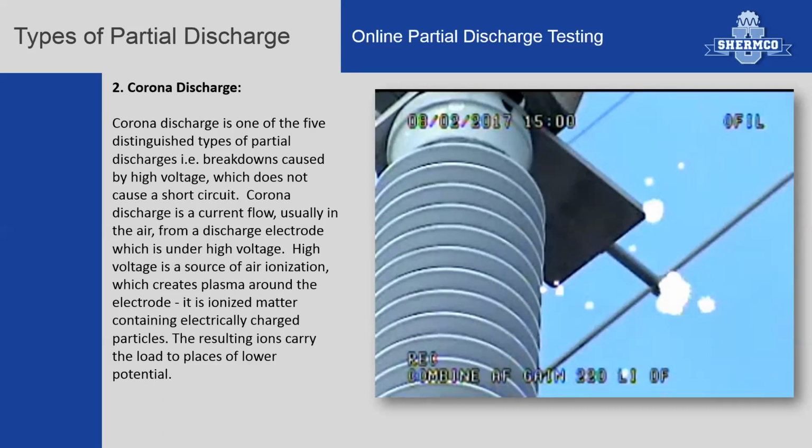In the acoustic, many of you may have already experienced, like on a hot, humid day, you're near a high voltage substation and you hear the hissing, crackling, and popping sound coming off the bushings. Again, if those discharges are into the atmosphere, into the water molecules in the air, they are relatively harmless in nature.